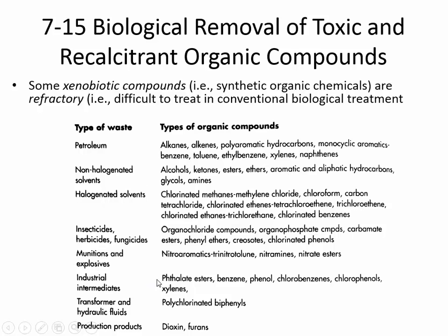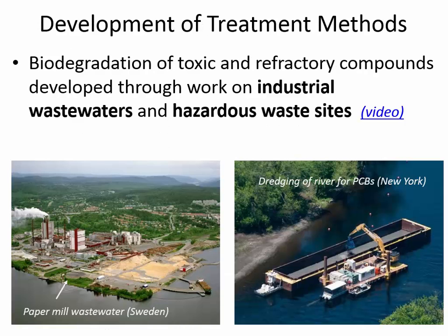So you see there's a list of these types of organic compounds that we're not usually very good at removing in wastewater treatment plants. The good news is that most of these shouldn't be present in our wastewater. If you think about it, you shouldn't be flushing gasoline down your toilet, and you're not supposed to dispose of chlorinated solvents into a combined sewer. So usually the concentrations are relatively low. We know the most about the removal of these types of chemicals just from specialized instances of the wastewater being broken down in industrial situations.